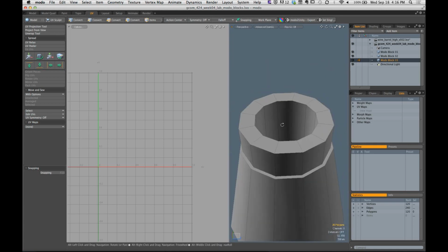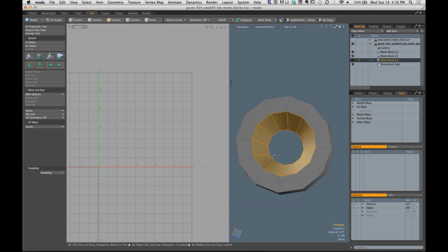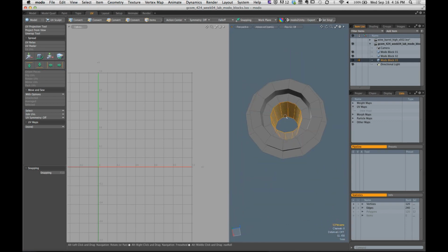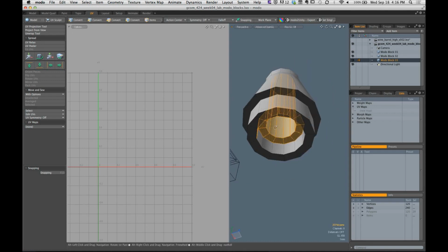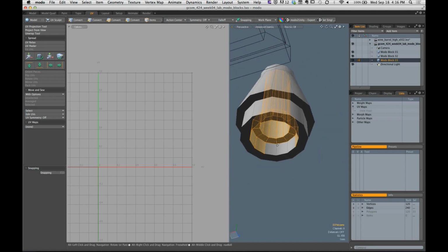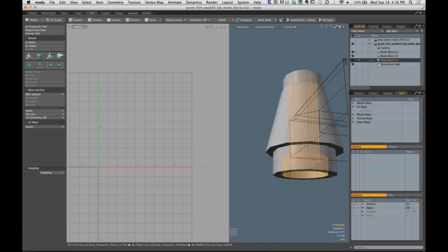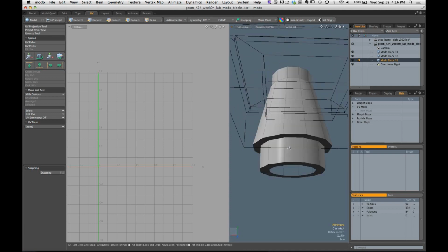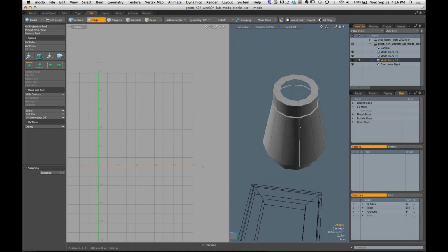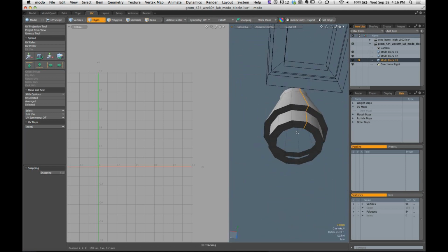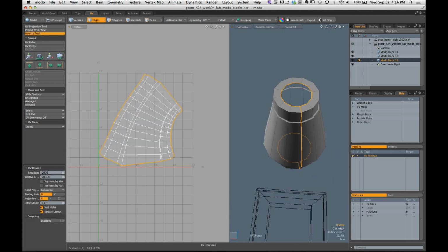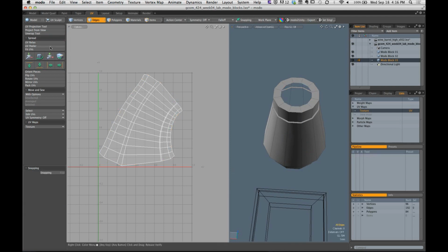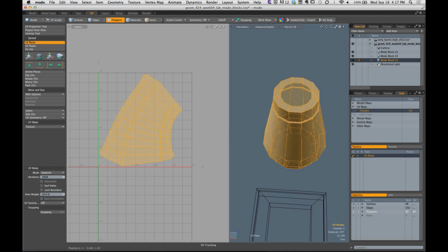I think the best example of that is Modo block number 3, which is going to produce a significant challenge. People try to unwrap it all in one piece. That's not going to happen. Do it in small little chunks, okay? Specifically, I put this hole in here to give you guys a little bit of a challenge to work with. Here's my strategy. I would do the inside separately from the outside. Okay, there's the inside. Let's just hide that geometry. Now, UV Unwrap is going to give you a much, much better result. I'm also going to select the borders here, the openings, and now UV Unwrap, better. You start to pair that with UV Relax. UV Relax. Okay, you'll get a good result.